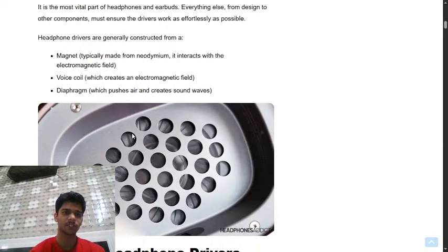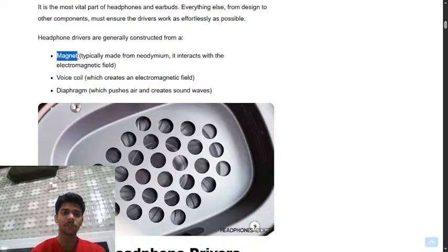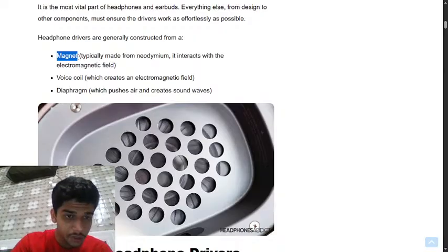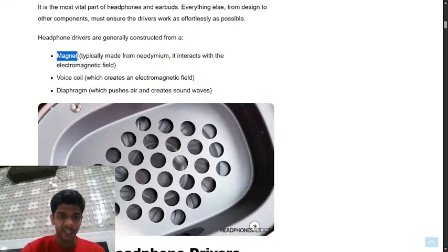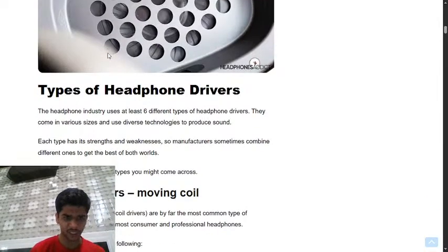Headphone drivers are generally constructed from a magnet, which interacts with the electromagnetic field; a voice coil, which creates an electromagnetic field; and a diaphragm, which pushes air and creates sound waves, the part from which we hear the sounds.